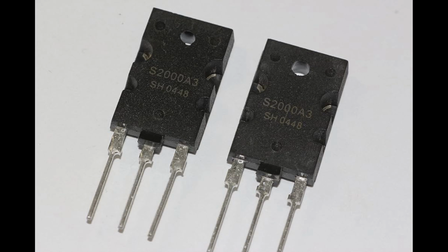Wien bridge oscillator: this oscillator uses transistors, often operational amplifiers with feedback networks, to generate sinusoidal waveforms. It's often used in audio frequency applications. Relaxation oscillator: transistors, specifically unijunction transistors, UJTs, are used in relaxation oscillators to generate square or rectangular waves. These oscillators are commonly used for timing and pulse generation.